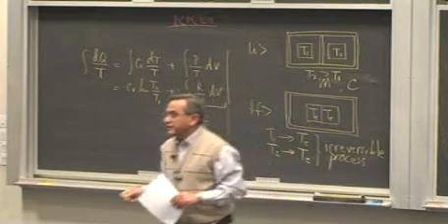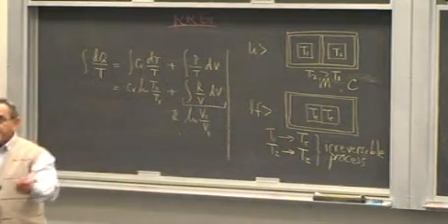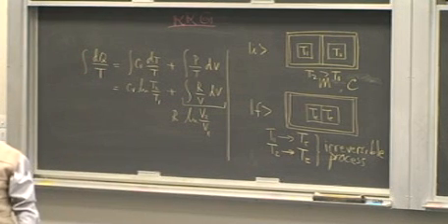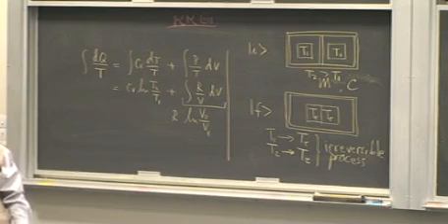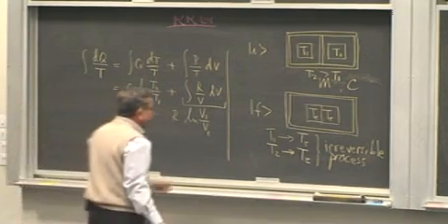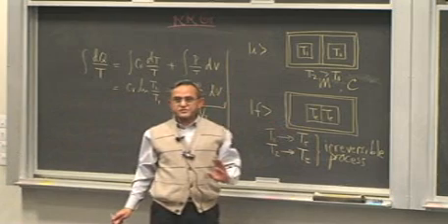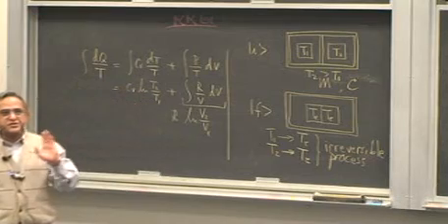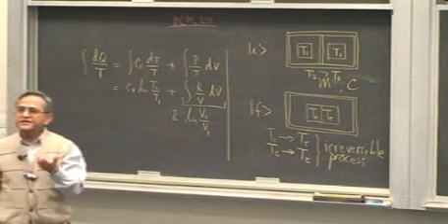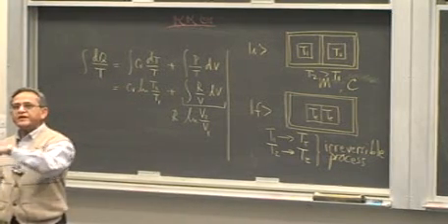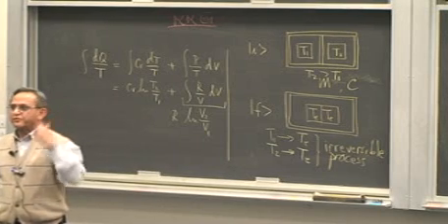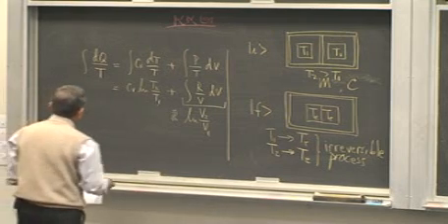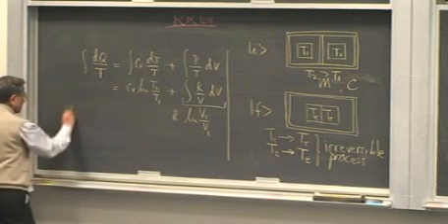Irreversible in the sense that you can't separate them out and they will again, one will go to temperature T1 and the other one will go to temperature T2. That just cannot happen. We all know that. Okay? So this is going to be an irreversible process. What we will do to find out the change in entropy is to turn this irreversible process into a reversible process, or a quasi-reversible process. So at times we in fact use the word quasi-static process.